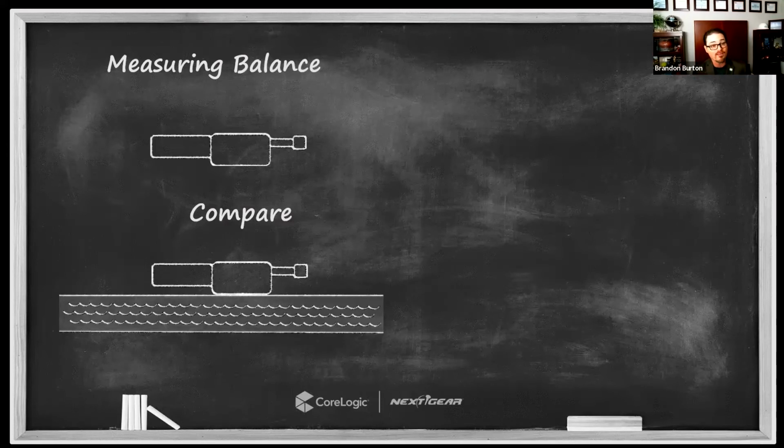So what is that comparison? How do these 2 compare to one another? And if the air that is in contact with the wet surface is substantially higher than the air above it, then we don't have enough airflow. Document it. Increase the airflow. Increase the speed of the movement across that surface, and then measure again. If the 2 are now comparable, it was a great adjustment. You will now have a faster drying rate, right? If that adjustment didn't correct the problem, continue to adjust, right?